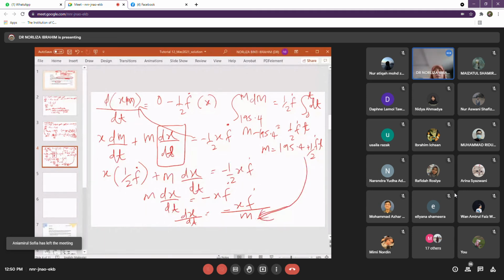Okay. Now, it's done on the component balance. Now, at t0, what is your x? At t0, what is your mass fraction? At time equal to 0, before you start the time, what is the mass fraction of your sodium bicarbonate in the tank? Refer to the dissolution process earlier: 0.9 kilomole of sodium bicarbonate over 100 kilogram of water.